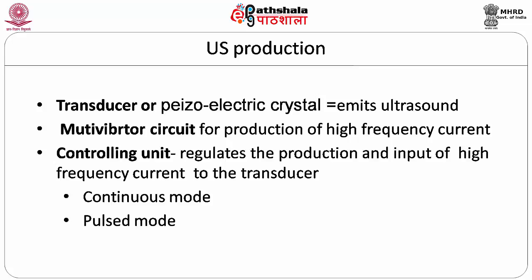The multivibrator circuit has a controlling unit based on an astable multivibrator which can turn the multivibrator circuit on and off, and it gives the pulses of ultrasound. A suitable resistance circuit is also provided to control the amplitude of electrical oscillation, and this regulates the intensity of the emitted ultrasound.